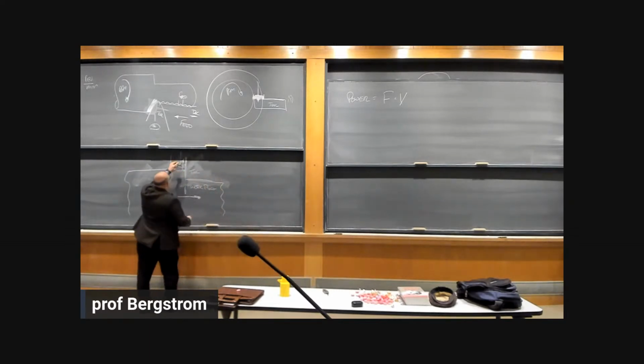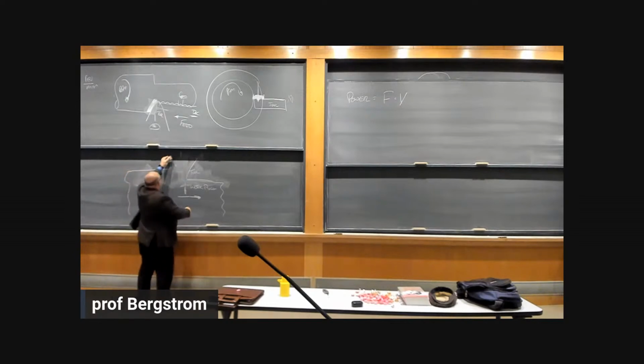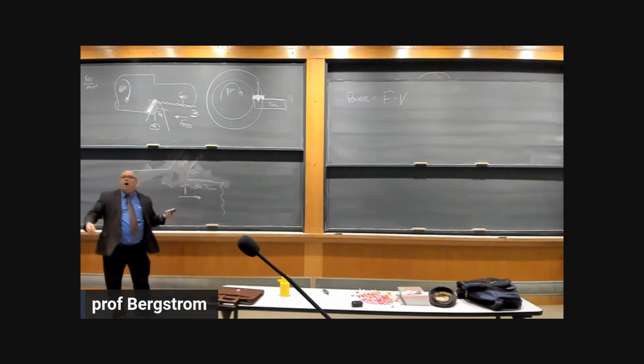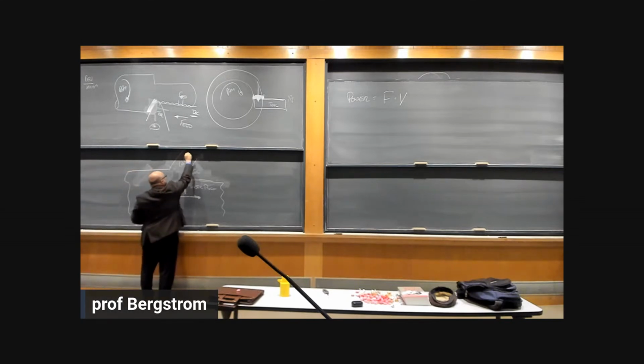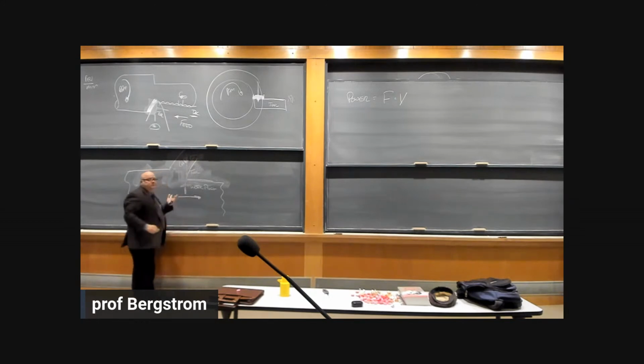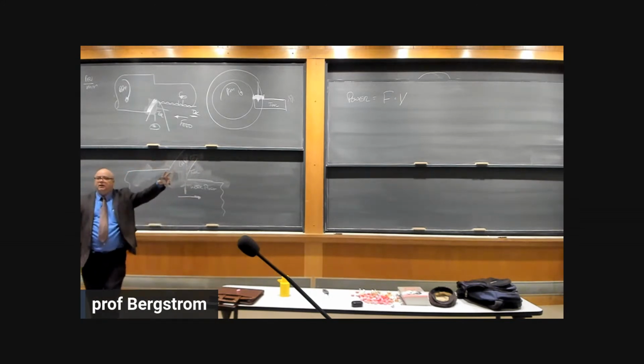We change the rake angle of this drawing. What we do is we make the tip back a little bit, and the chip's going to form and flow that way. And so we'll call this a positive rake angle. And we measure it from the vertical. And we use alpha. So positive rake angle is alpha, it's this angle right here.